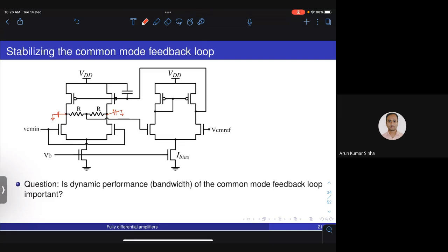No, see, essentially this amplifier will have two poles. One is the output pole here. Let me call this P1, and the second pole will come because of the load capacitance on the output. So let's say this is some P2. By putting this Miller capacitor here, you are basically pulling P1 to be much smaller than P2. That is what the Miller capacitor is doing.